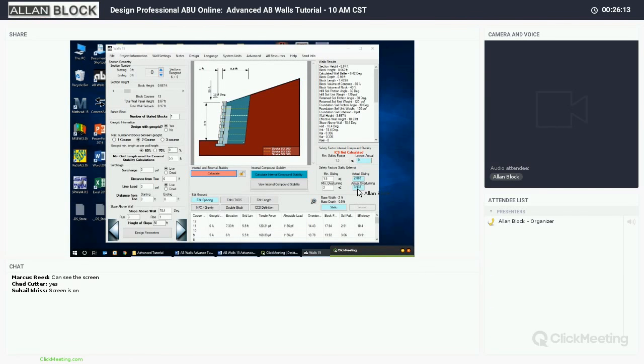So what does that mean? Let me go ahead and hit OK and hide. Notice how all of the slip arcs, or at least the lowest safety factor slip arcs, are being shown and they're converging to this last point on top. Remember I was talking about the wall envelope. This wall envelope was twice the wall height, or the effective height plus the grid length.